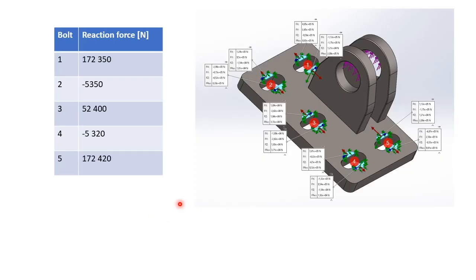This is a simulation that was performed. This is a flange with two ears, and there's a bolt going here and it's pulling it upwards. And we added a lot of holes around here, and we tried to calculate. If we assume that the normal force here would be evenly distributed, it would be a fifth of the force on each hole.